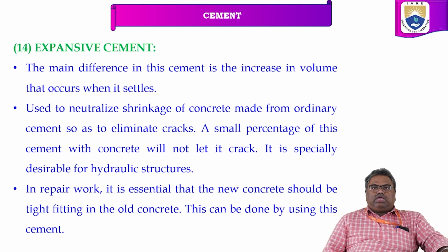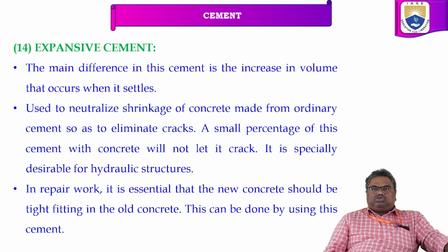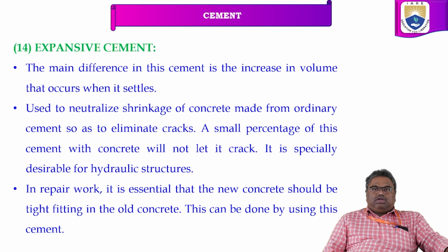We use it to neutralize the shrinkage of concrete made from ordinary cement, so as to eliminate cracks. So the property is expansive. The concrete will expand, so it eliminates the minor cracks that develop. A small percentage of this cement in concrete will not let it crack.